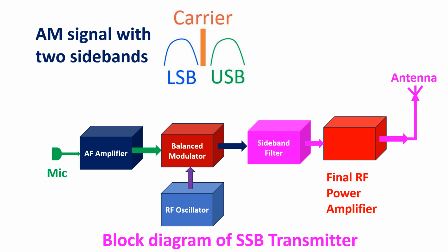Removal of the carrier removes the bulk of power requirement in an amplitude modulation transmitter. Only a small portion of the power is carried in the sidebands compared to the carrier wave. So, if only one sideband is amplified and transmitted in SSB mode, the received signal will be at least 4 times as much as the AM signal for a given power input to the final RF amplifier. Conventionally, lower sideband or LSB is used for frequencies below 10 MHz and upper sideband or USB for higher bands.